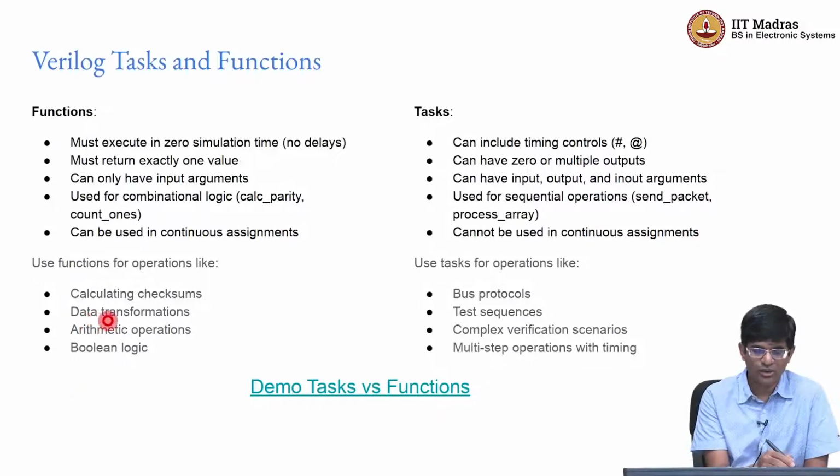And if we want to use it for operations like calculating checksums, performing simple arithmetic operations, Boolean logic and so on, it's a very nice way of making your code more modular and easy to understand. Tasks in that sense are actually more powerful, right. They actually can include timing constructs like delays. They could have 0 or multiple outputs. They can have input output.